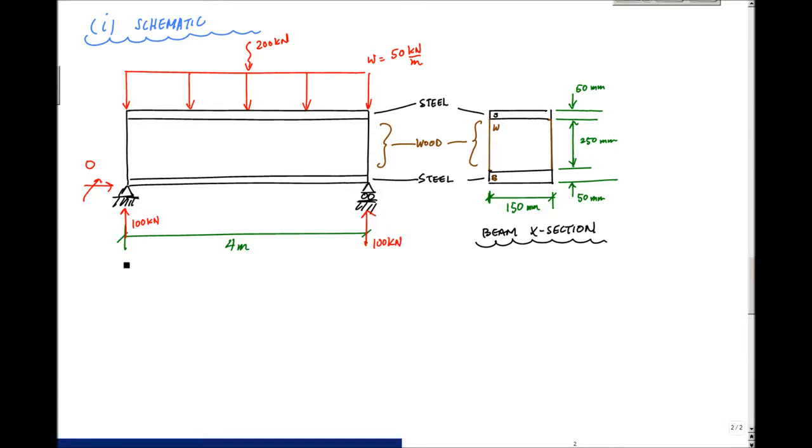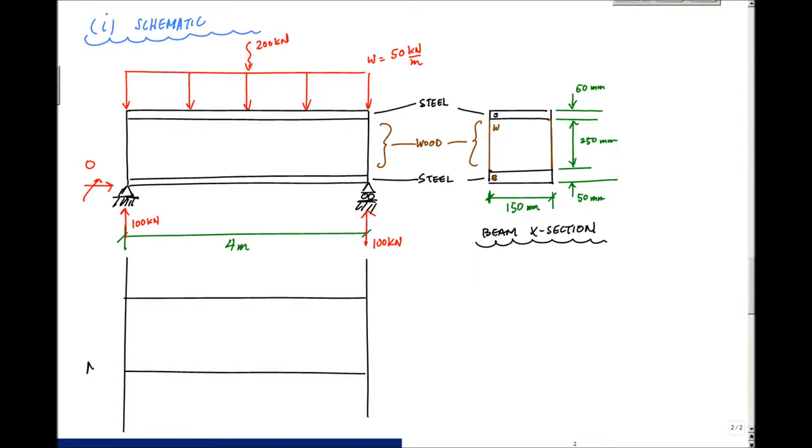So here, let's see, got my straight edge. Okay. Got my straight edge, got my horizontal line for the shear diagram, got my horizontal axis for the moment diagram, the moment in kilonewton meters, and the shear in units of kilonewtons. And really, the story is, if you're not sure, go check out a video or ask your instructor, right? 100 kilonewtons to start, or some people say go up 100 kilonewtons right here. And then I decrease linearly at a rate of 50 kilonewtons per meter, or I have a slope of 50 kilonewtons per meter. And let's see, the middle is right about there. So I want to make sure I hit the middle correctly.